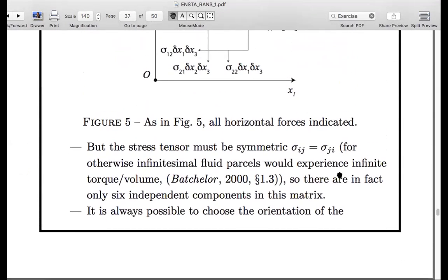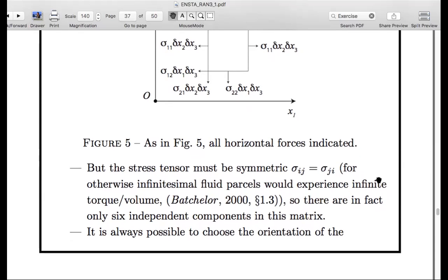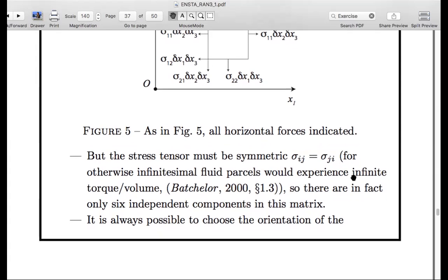But maybe for those who haven't heard this before, just trust me, whenever you have a symmetric matrix, you have the possibility of choosing a different coordinate system. It's still a rectangular Cartesian coordinate system. You've just changed the orientation of the axes via rotation, right? You didn't move the center, you just rotated the axes. Sorry, I guess that's hard for people at home to see, but you're keeping the origin the same, you're just rotating the axes. That changes the components of this matrix, right? Because it's a tensor, and you can choose.